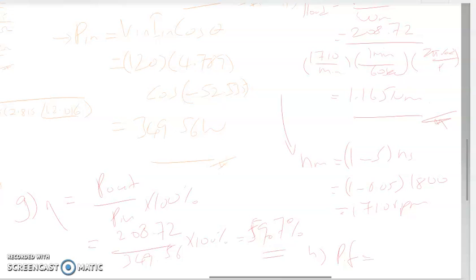And so also the power factor, which is cos theta, the angle of current compared to voltage, which we got just now, 52.535. Negative means that it is lagging, so the power factor is 0.608, and the efficiency is almost 60%. So that's settled for question 9.1 in the example on page 614, if I'm not mistaken. So we shall use this question for 9.3 as well.